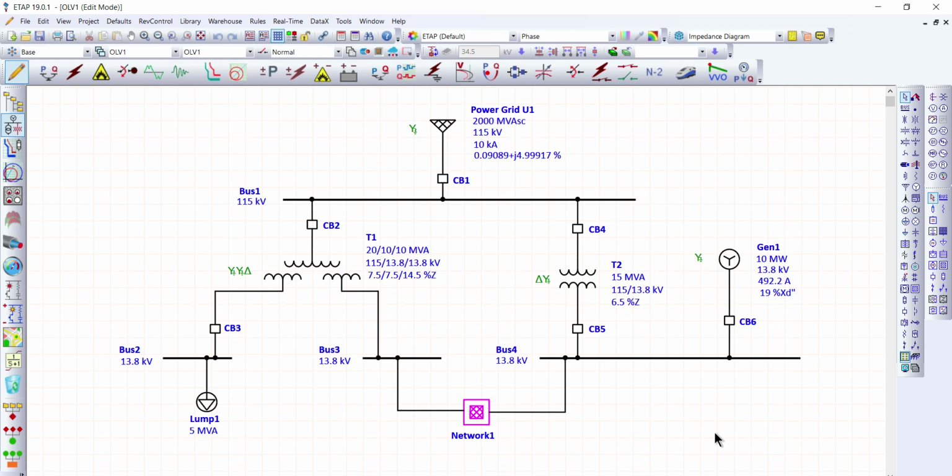85% of all faults in power systems are line-to-ground faults. Line-to-ground fault is rarely greater than three-phase fault in industrial systems. Normally, line-to-ground fault is roughly equal to 87% of three-phase fault. The three-phase fault current condition is usually the only one being considered in industrial systems, since this type of fault generally results in maximum current.